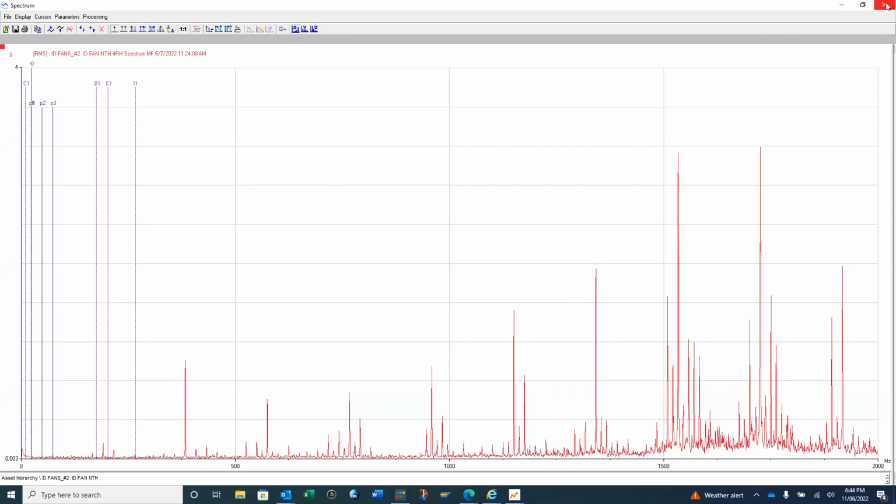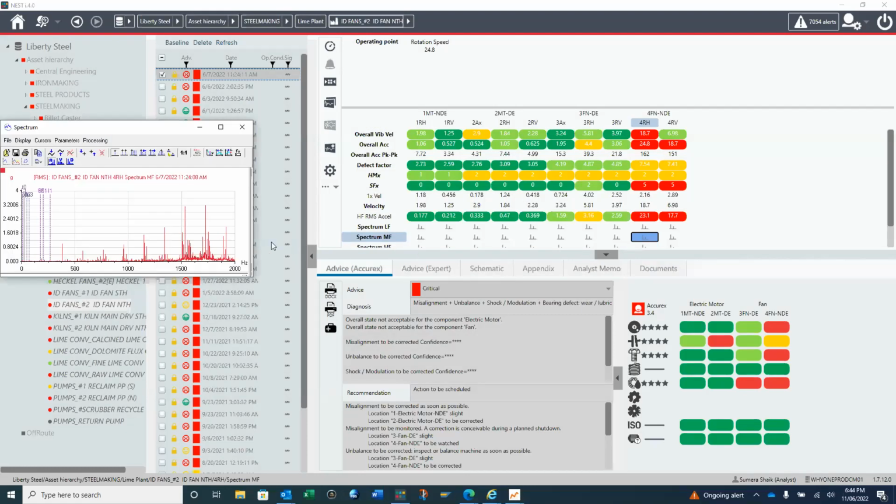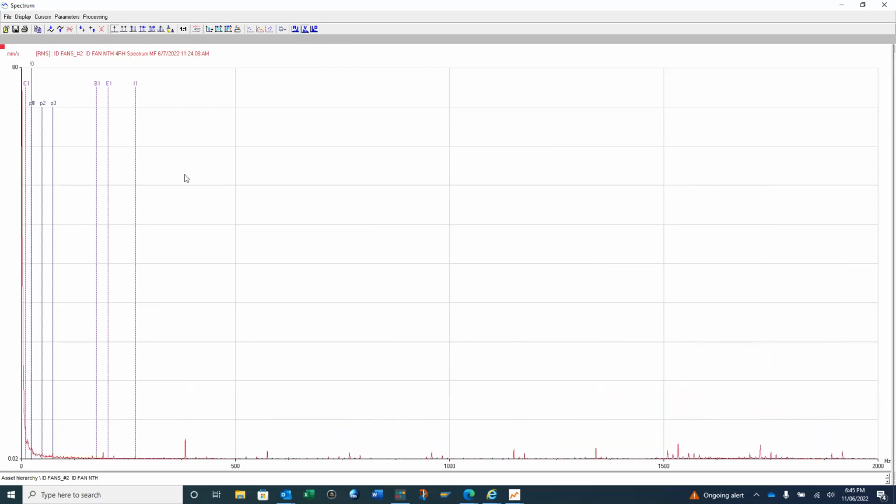That peak is always there or sometimes not there? No, it's not there. I'm not seeing it in any trend. So it's impossible that 2.25 hertz and then 60 mm per second and then low frequency. This is the medium frequency, and in velocity it's very low. It is 80. Can you see here? 80. Yeah. 1.87 hertz.